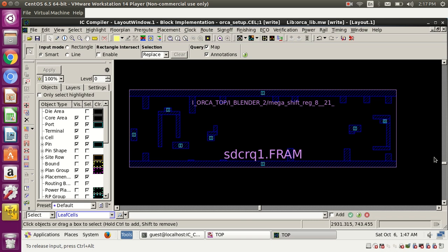We can allow some variation, like 10% or 15% of our clock period, in insertion delays. But the difference should not be like this one is 10 ps and that one is 100 ps. That is almost triple, like 5 times. It should not be like that.